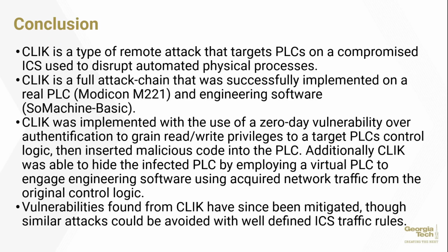So, as a conclusion, CLIK is a type of remote attack that targets PLCs on a compromised ICS to disrupt an automated physical process. It's a full attack chain which was shown to be successfully implemented on a real PLC, in this case the Modicon M221 PLC, and engineering software, in this case the SoMachine Basic engineering software. CLIK was implemented with the use of a zero-day vulnerability. This vulnerability took advantage of the authentication to grant read and write privileges to the target PLC.